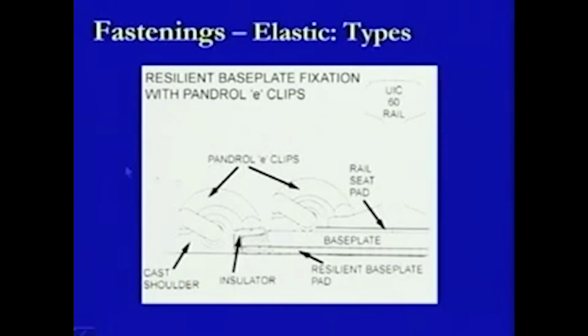In this one, what we are seeing is a connectivity of the rail section where the base plate is also being used. Now, when we are using a base plate, we can see that there are two Pandrol clips which have been used here. One Pandrol clip is trying to fix the rail section on the base plate, and the load is being transferred at this location, that is how it remains in a fixed condition.